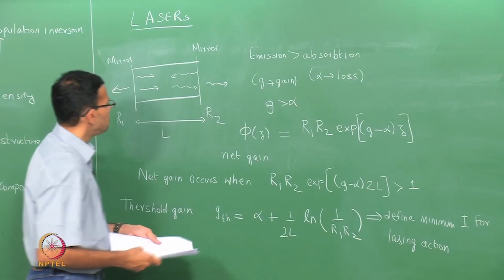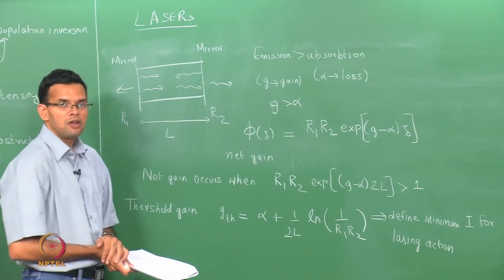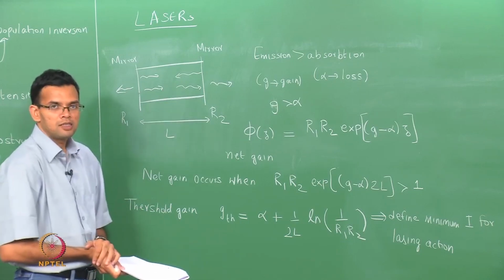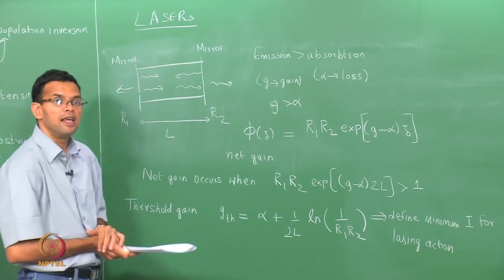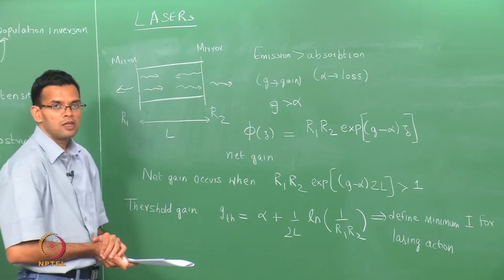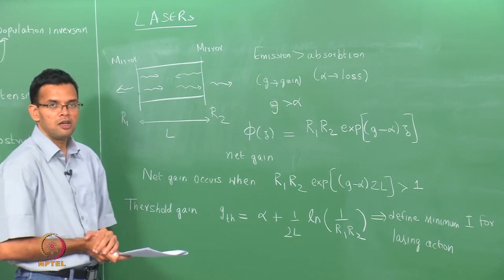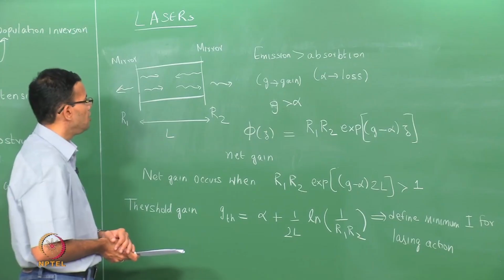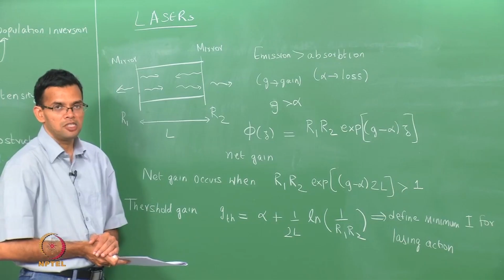So, in this particular example, the two reflectors help to confine the laser in the plane of the device, but we also need to confine the light within the active layer, so that light does not escape from the top or the bottom. This is done by usually choosing a graded structure with different refractive indices, so that you have total internal reflection and the light is kept within the active region.